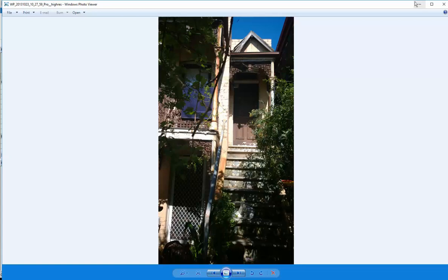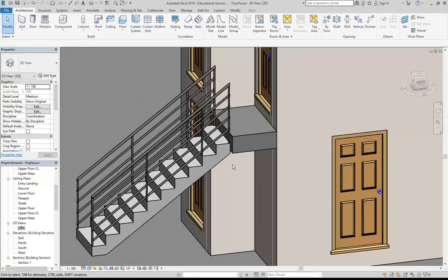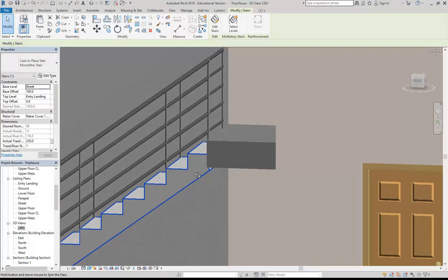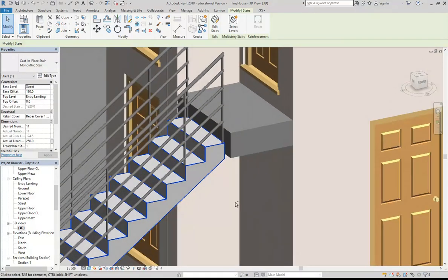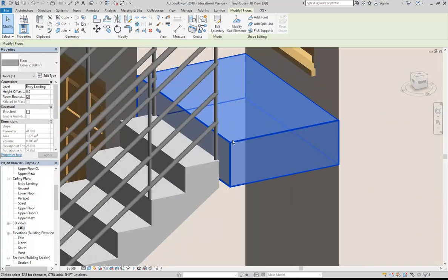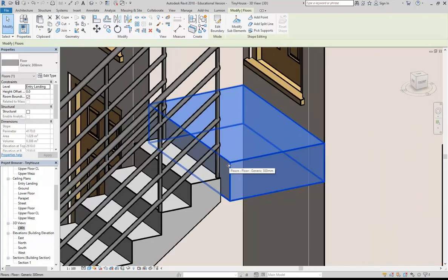Yeah, it does depend, but it's a bit tricky with concrete stairs because they do need enough depth to engage with the floor. And there are ways of extending them in other ways as well. But yeah, look, just to do it quickly, it's not a bad idea to make the floor deep enough to connect to the stair. Maybe 300 is quite thick though, so maybe I'll just show you how you can change this to something in between. That might even be better.